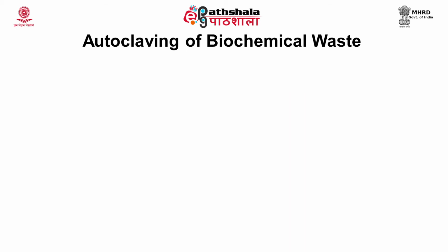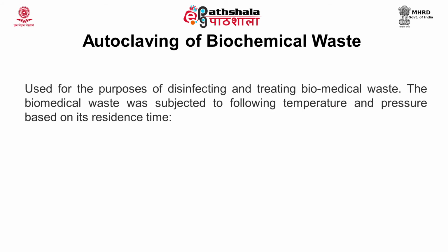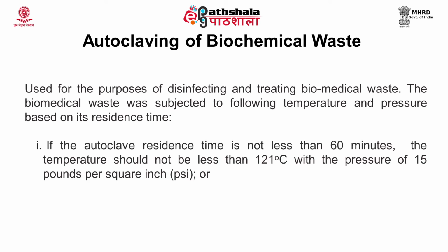The next type of treatment method is autoclaving. Autoclaving of biomedical waste is popularly practiced. It is used for the purpose of disinfecting and treating biomedical waste. The biomedical waste is subjected to the following temperature and pressure based on its residence time. If the autoclave residence time is not less than 60 minutes, the temperature should not be less than 121 degrees Celsius with a pressure of 15 pounds per square inch, or psi.